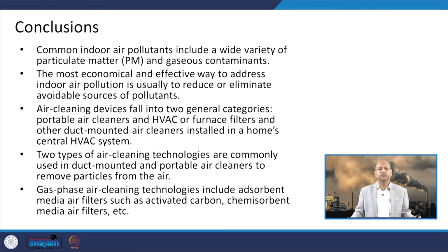And the two types of air cleaning technologies are commonly used, duct mounted or portable, as I said. Then gas phase air cleaning technologies include adsorbent or absorption media, activated carbon, and chemisorbent media filters. Then there are other technologies like plasma and ozone related ones which we have seen, but they need very skilled people to handle them. So, they are used only in industry related installations where indoor environment and occupational hazard issues are there and well trained people are there to handle those kinds of devices. Otherwise, we can go for simple filters and proper ventilation in residential areas.